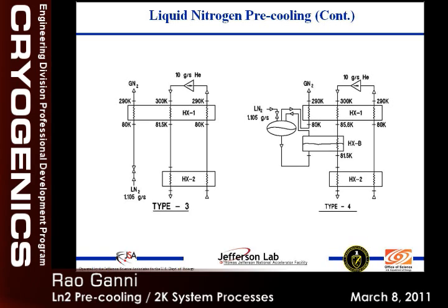Nitrogen itself doesn't expand when it is thawed, but because they are layered, you have helium, you have nitrogen, you have helium, high pressure helium and low pressure helium. The low temperature helium freezes the nitrogen, but it doesn't freeze equally because of the flow maldistributions. So when we start warming up, we have the danger that we can warm up on the top end of some of the passes, and some get warmed up in the middle and build up very high pressures, while both ends are still frozen. We have had heat exchanger failures a few times from the pressure build-up in the middle, with both ends still frozen with the nitrogen.